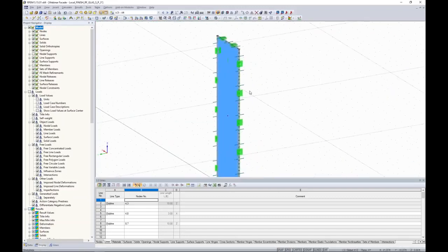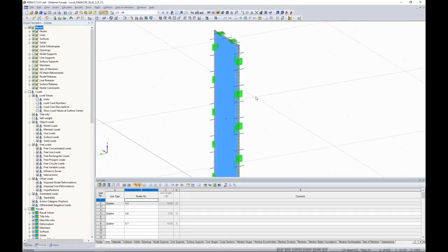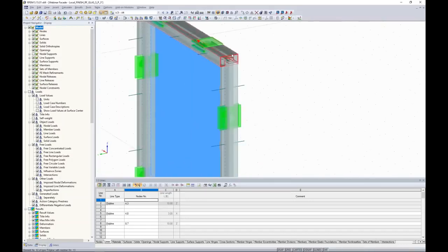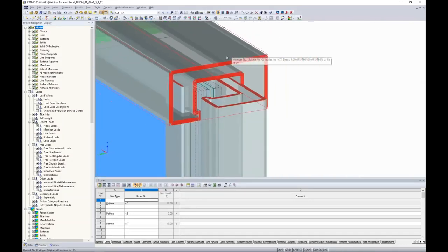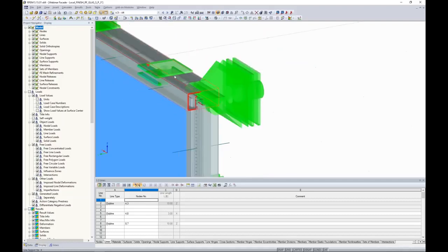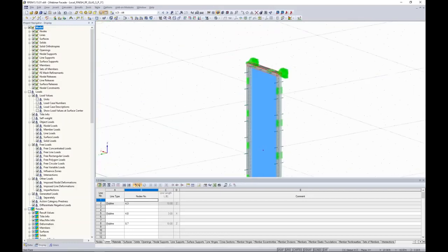So the other thing you'll notice too, these are my helper supports. Those are those rigid connections that the program's placing at the edges to make sure that we get desired deflection. Again, the boundary members are shown here. Here's my custom shape thin section shown, as well as the nodal supports. So those nodal supports are defined on the individual layers that I applied it to. So this is what's going on behind the scenes.